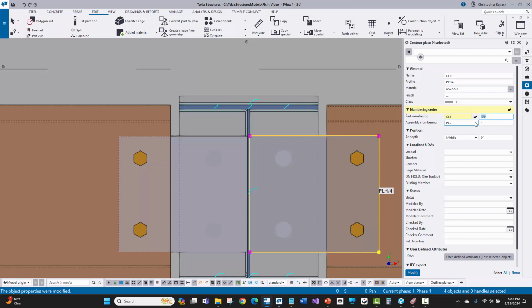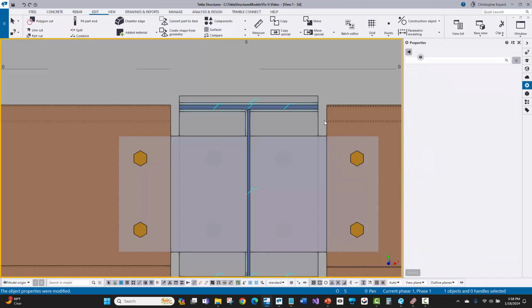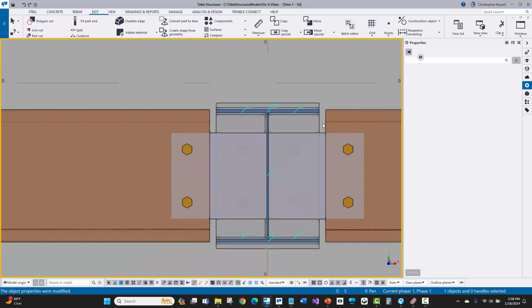So this is something important you got to make sure you remember to do, because what was happening there with the negative numbers before is it was forcing standard clips importing in from SlideRule. So if you had DT clips set up in MBS and you had basically standard part marks or standard clips, those start numbers get forced, and you want to make sure that you clear those out if you're going to make a non-standard clip scenario like we are here. So there we go. We've got that actually fixed up.